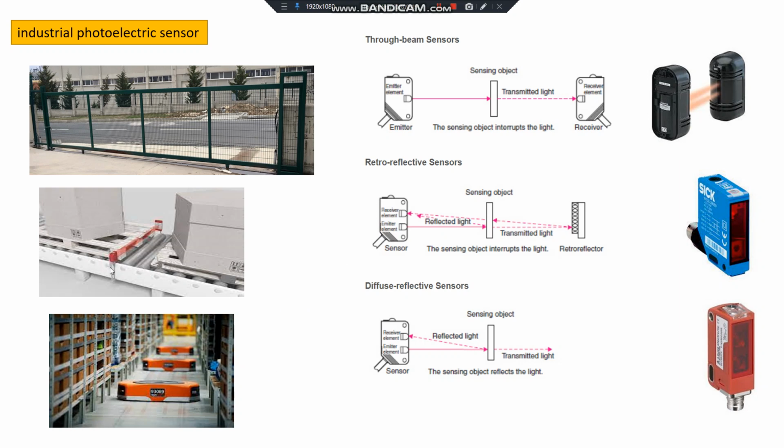In the examples, there is a container here, and there are sensors located on one side. On the opposite side there is a reflector. These sensors see the reflector and are activated when there is a box coming between them. This will send information to the PLC, and in this way we can understand that there is a box coming across the container.